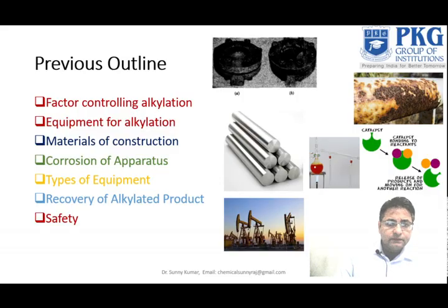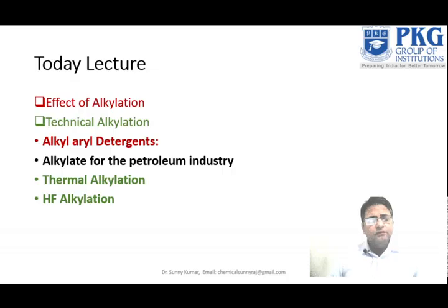In today's lecture we will discuss, first, the effect of alkylation. What is the effect of alkylation, and then the technical alkylations. In the technical alkylation we will discuss alkyl aryl detergents, alkylate for the petroleum industries, thermal alkylation, and hydrogen fluoride alkylation. We will discuss how we can produce the alkyl aryl detergents, and how they are different from the petroleum based detergents.